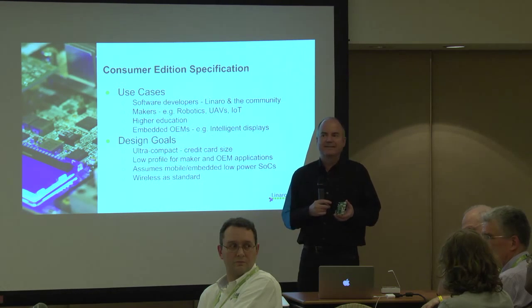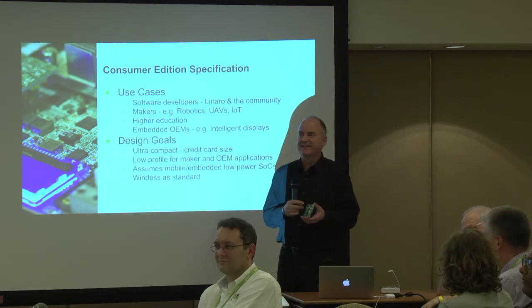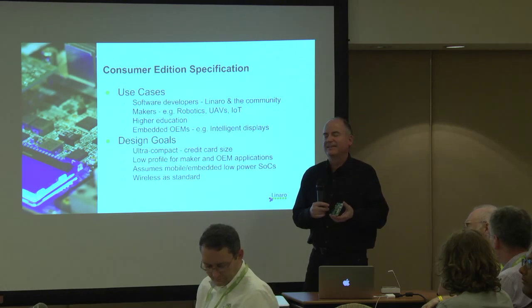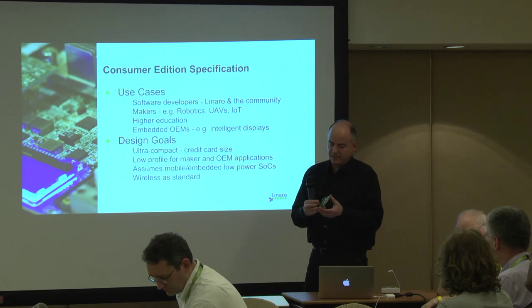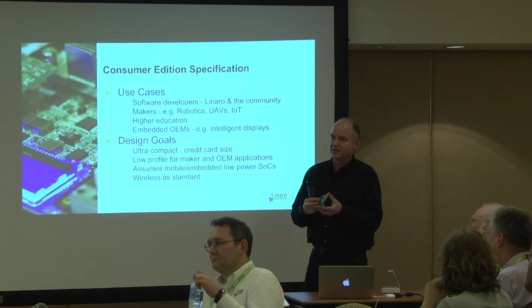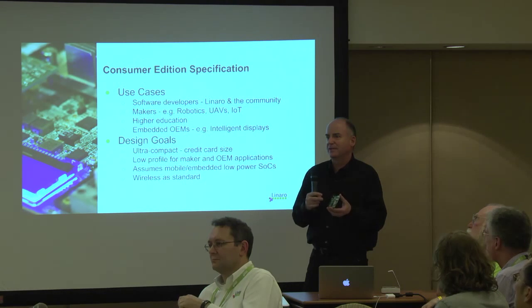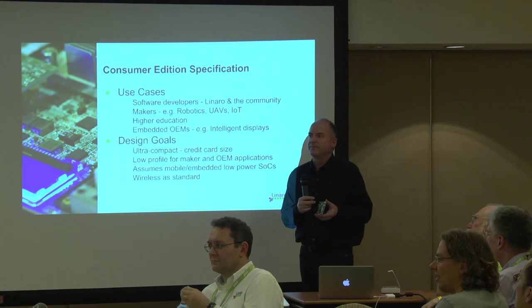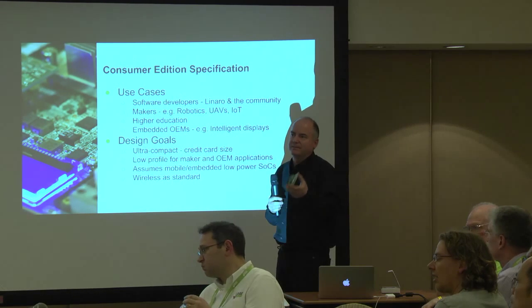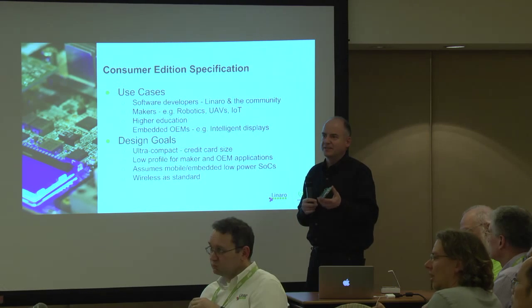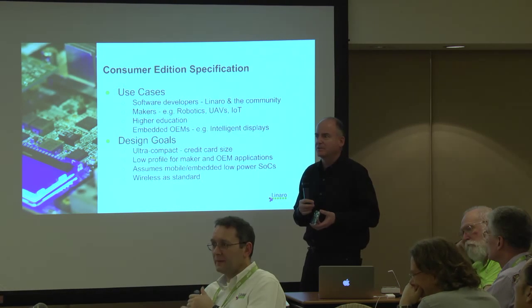Right, but as you say, it's a compromise between being able to use the board in real things versus being a bit more convenient for developers on the desk. So what I suspect is that somebody will come up with a very small little board that plugs onto here and brings out the UART onto an FTDI USB. Yeah, and then it'll work on any board. That's the nice thing. People want to do these convenient things. It'll then just work on anybody's board.